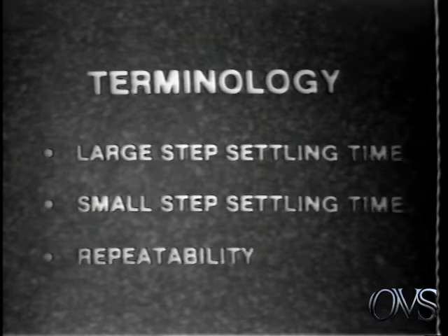Repeatability is another display specification. This is an expression of how accurately a given set of X and Y input voltages will repeatedly reposition the beam to the same point on the CRT face after the beam has been deflected from that point with any other on-screen X and Y input voltages. Repeatability error is usually specified as a maximum % of full screen deflection.